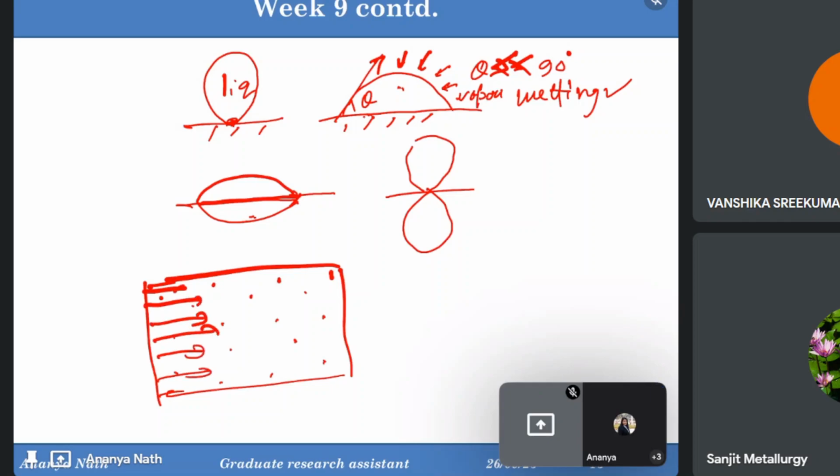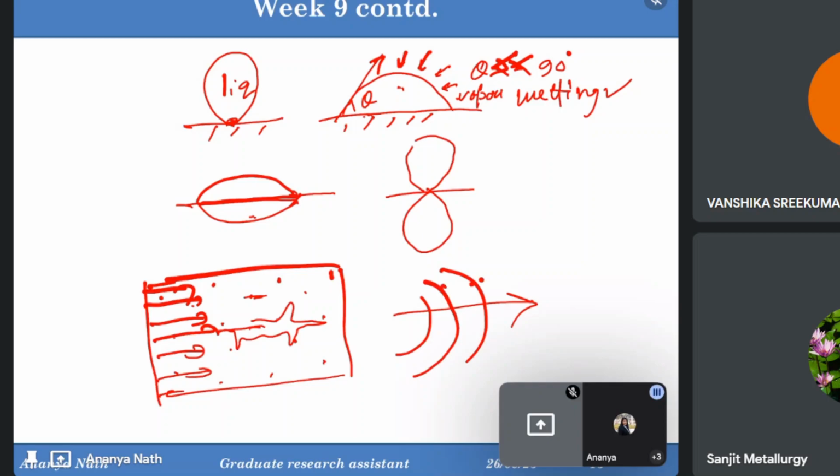Depending upon the time that we keep the material for solidification, or the temperature we provide, there can be protrusion and dendritic formation, and those can hamper the distribution of SiC. If this is the temperature front, moving from this direction to this direction for the solidification purpose, then with the solidification front, the SiC can get agglomerated.